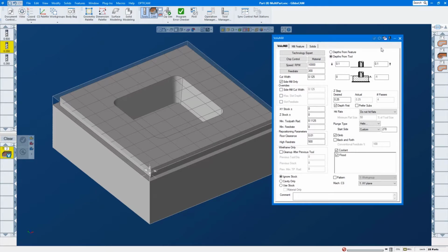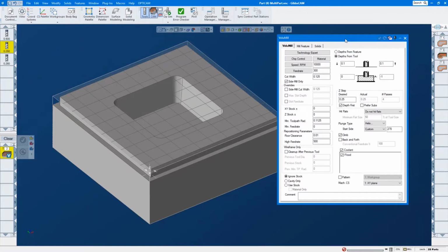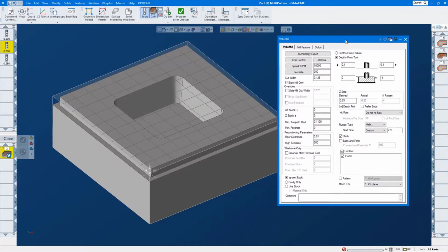But because it's going to do that, it has to have enough room to hit the entire helix all the way down, so it doesn't over-engage. Okay, that makes sense. Even if you're using a flat bottom drill. So it might seem like you could use a smaller drill, but you can't because of the way its logic works. So the toolpath is calculated as if there is no hole there, right?